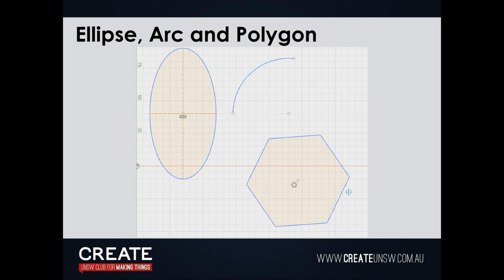So polygon, right? Circumscribed polygon. Start here, for example. If we wanted an octagon, you just hit 8 and it does that for you. If you wanted a dodecagon, same, 12. Once it gets to 16, it pretty much becomes a circle. We'll just do an octagon so you can still see it. You can manipulate your dimensions, 70 mils right there.